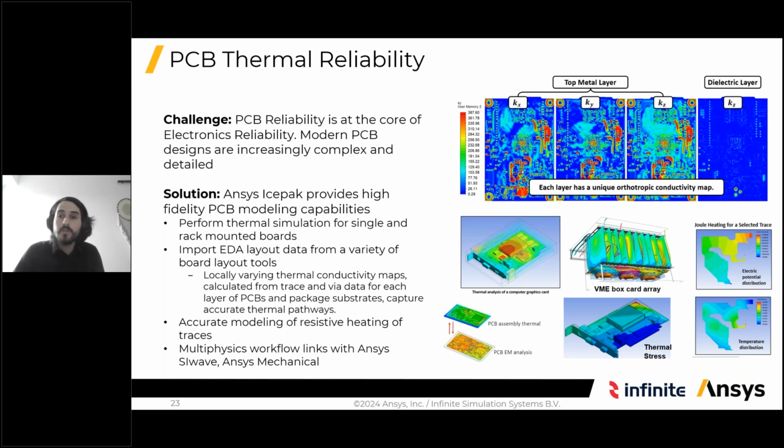So in this case, we can have what-if scenarios and investigate how to cool the board using maybe different strategies. Maybe we can just switch some component and then we will have a better thermal behavior. Or by separating some components, we can have a better thermal map. But of course, we can also do a what-if scenario of different heat sinks.